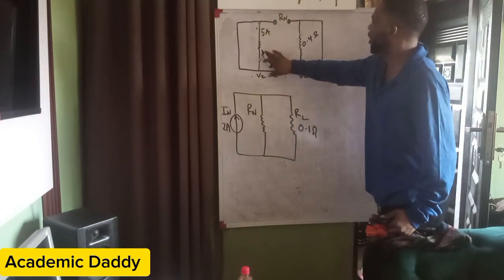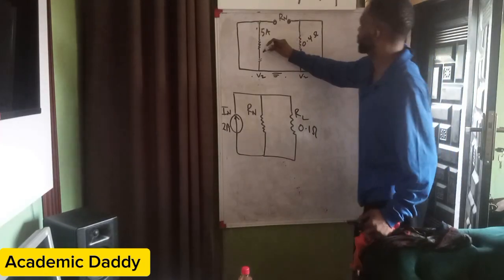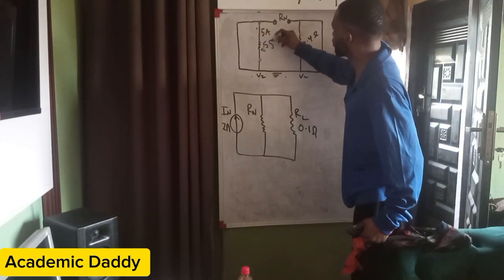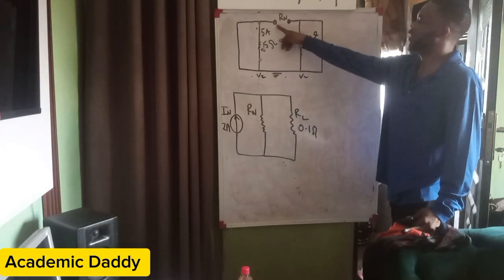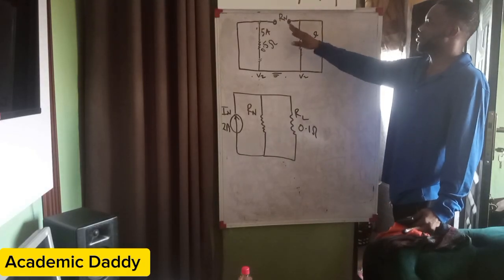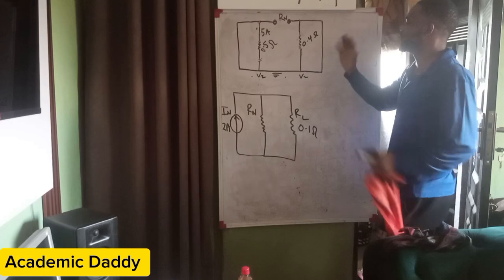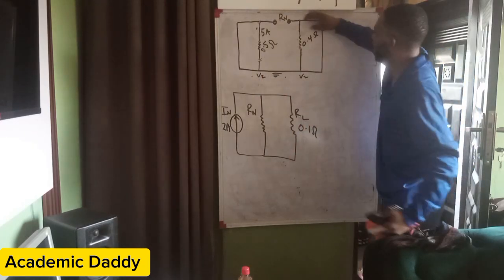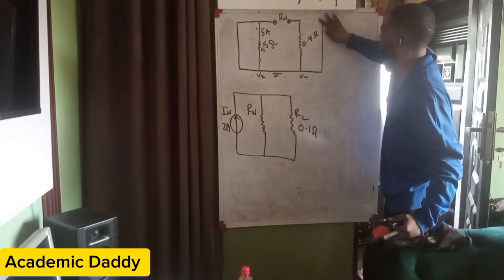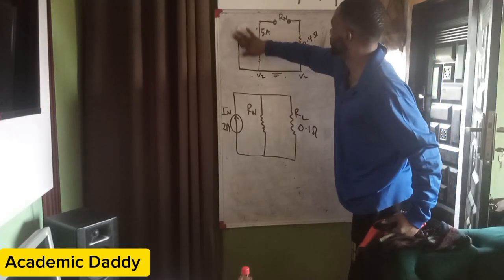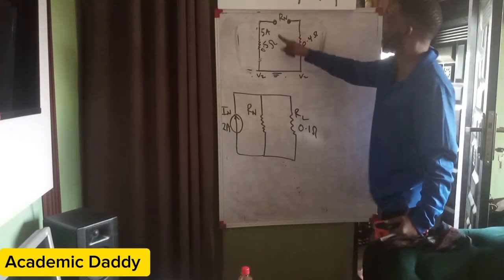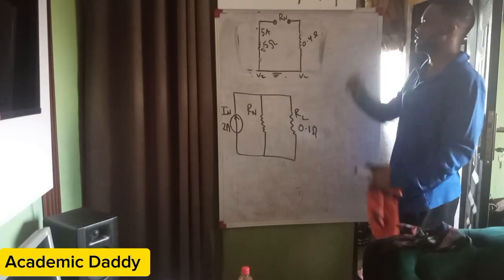So that means all I have is just the 0.5 ohms resistor and the 0.4 ohms resistor. The one that is giving the load is short circuited. It's more like you are standing here to view it. If you view it now, you see that this is wire. This wire has no use. It's the same thing as saying if I clean this wire that is here and I clean this wire that is here, you see that what I have is simply something that is in series.